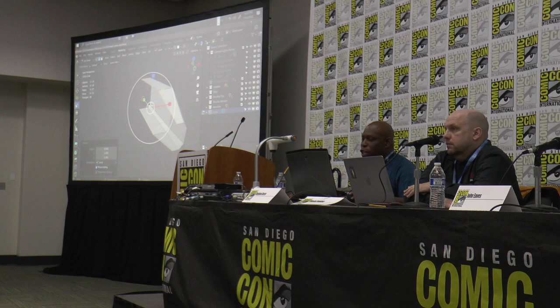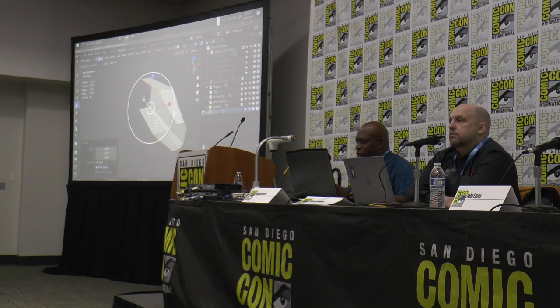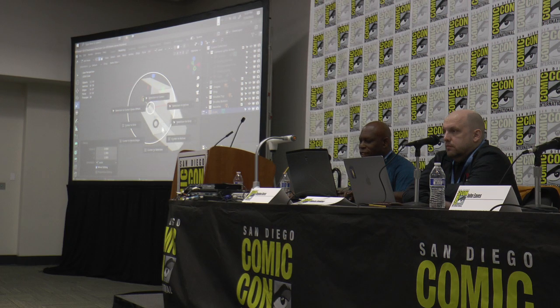Now I'm going to do something else. I want to put the 3D cursor exactly dead center where these slices are, because I want to mirror this and let Blender create that, bring the shape back, but using a modifier. We're going to talk about modifiers in just a little bit. So, Shift S, cursor to selected. Good. Now let's get out of edit mode. We're done editing, or almost done editing. Tab key, object mode. Okay, there's my object.